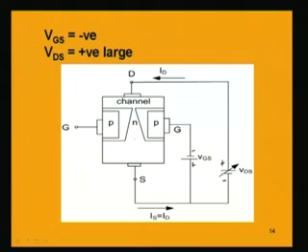When we have a small VDS, whatever was the region width in the depletion layer will not be the same when you increase the VDS, because increasing the VDS means that the reverse biasing potential for these PN diodes or the PN materials will now be increasing towards the drain side.